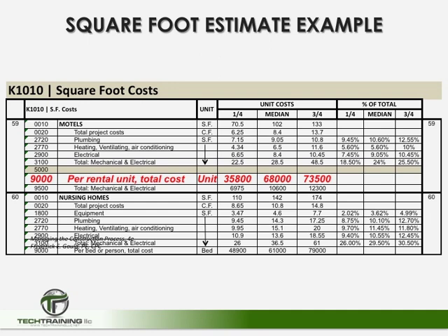And this also relates to the 1/4, where 1/4 suggests a lower quality, where only 25% of the projects used to gather the data are less expensive. Now we're doing a conceptual estimate and we are doing it per unit. So where it is bolded in red, we see per rental unit, total costs, and then it says unit. And for the cheap unit, it's $35,800 per unit. For the median, it's $68,000 per unit.